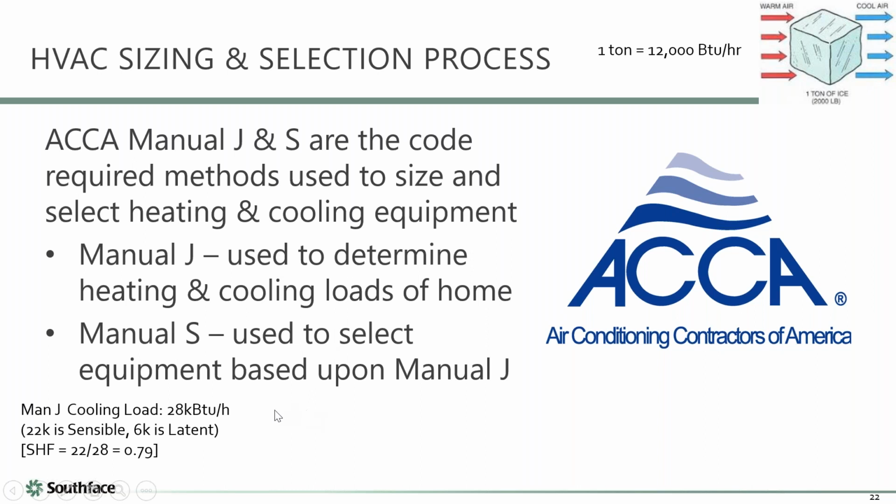So our choices here, you go, okay, that's about a 2.5 ton air conditioner. And so we look at this nominal 2.5 ton air conditioner. I say nominal because the manufacturer calls it their nominal 2.5 ton. I always think it's interesting that they're lying, because it doesn't actually do 2.5 tons. It only does 29,000 instead of 30,000.